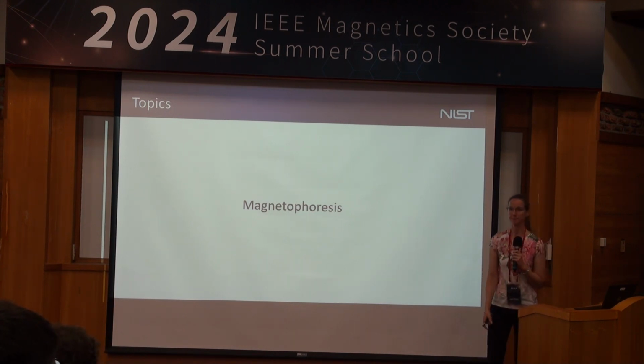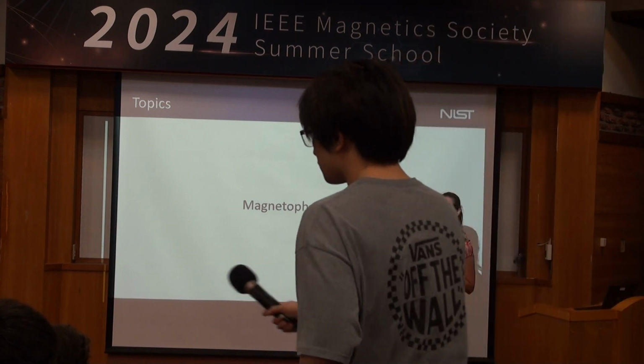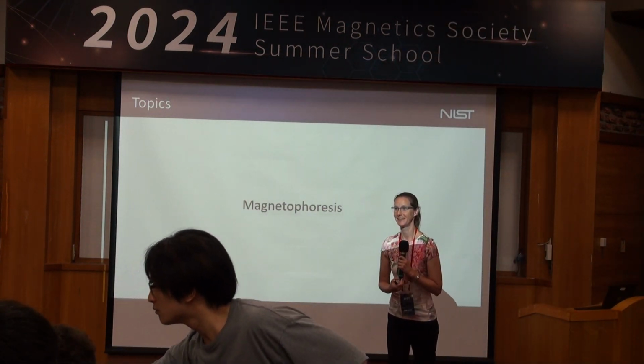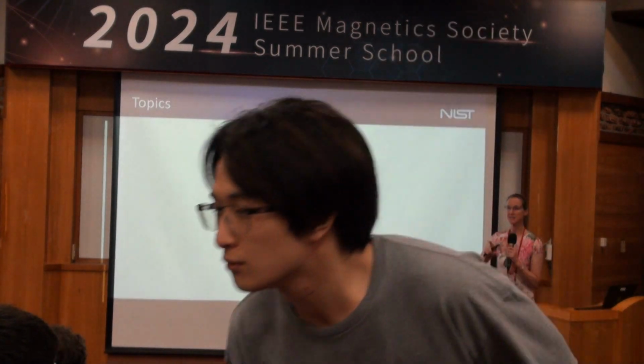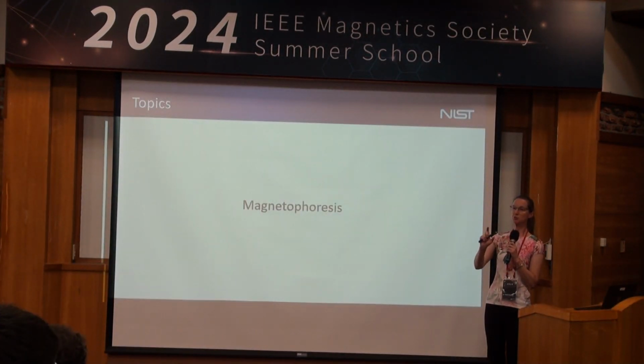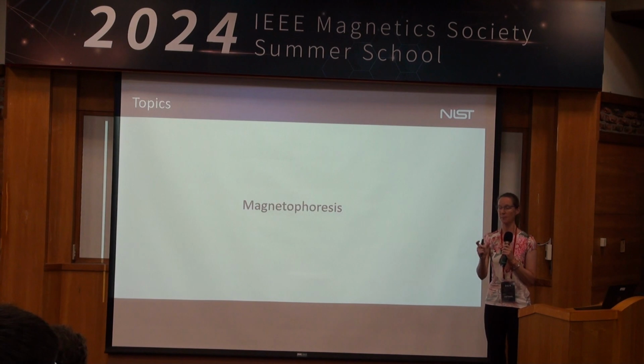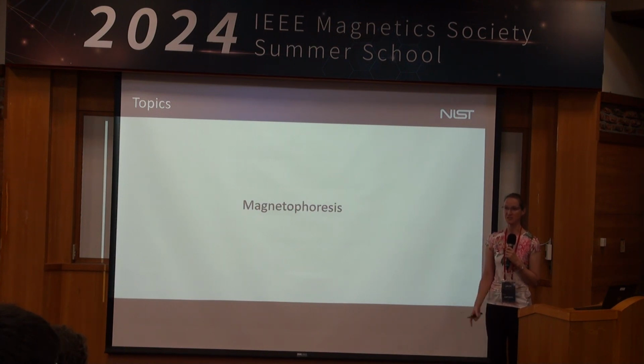It's targeted. Yes? Is there a reason you use GMR stacks as opposed to TMR stacks? The reason is because you want an MR that will change with small changes in the alignment of the layers, and TMR, because of the resistivity, is not going to give you that. And part of it is also just historical, in that GMR sensors already existed, because this work started about 20 years ago. Thank you.